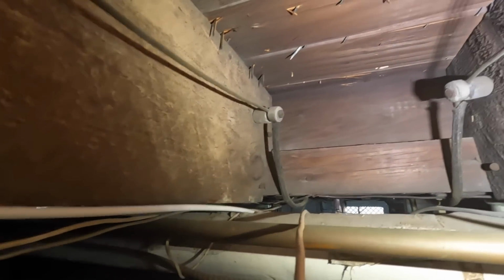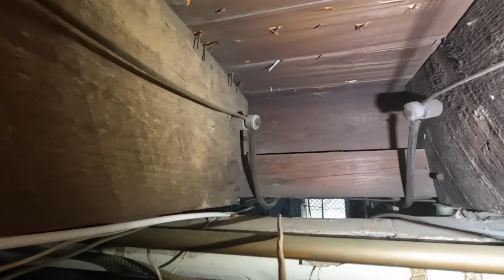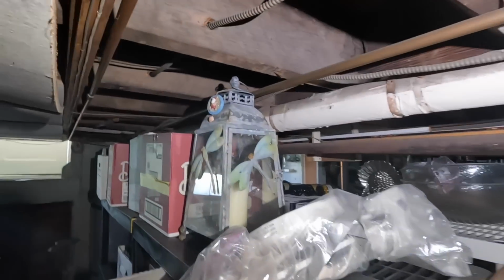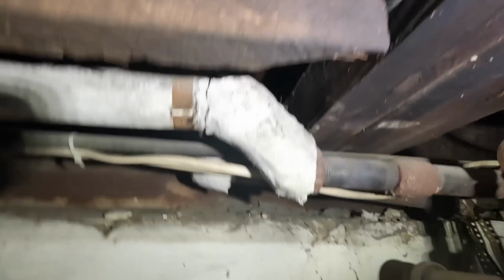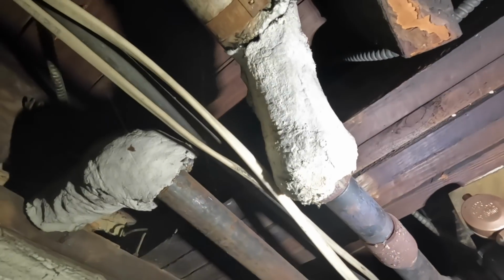Now, as you can see here, there is some armored cable, the BX cable, that's connected to the knob and tube going to some device boxes like the receptacles and the switches, that sort of thing. However, upon further investigation, I found that a lot of those BX cables were not properly terminated to the metal boxes. Therefore, there was no equipment grounding conductor there anyhow. So that all has to come out, and we need to either install a new box or connect to the existing box if that's possible.